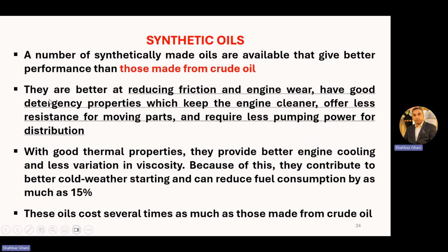Synthetic oils are better at reducing friction and engine wear, have good detergent properties which keep the engine cleaner, and offer less resistance for moving parts, so there is easy starting, and they require less pumping power for distribution, so they are easy to move around in the channels.